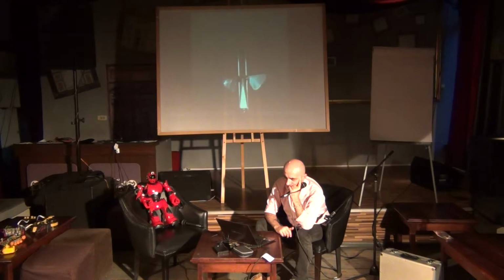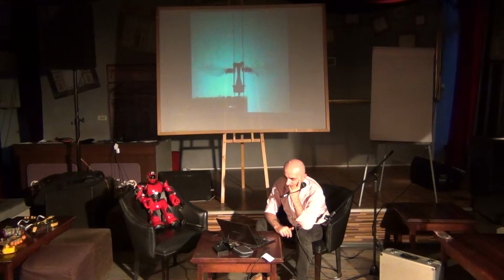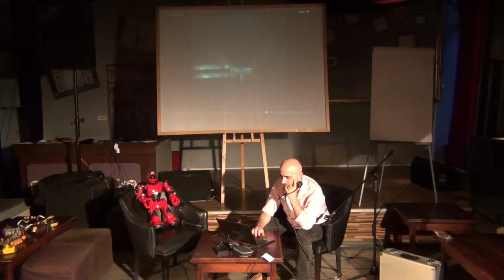After integration, the fly is fixed to guide wires that restrict the motion so that the fly can only move vertically. The wings are then driven open loop to achieve a large angular displacement. This is done at resonance to further amplify the wing motion. The wings exhibit a trajectory nearly identical to biological counterparts.